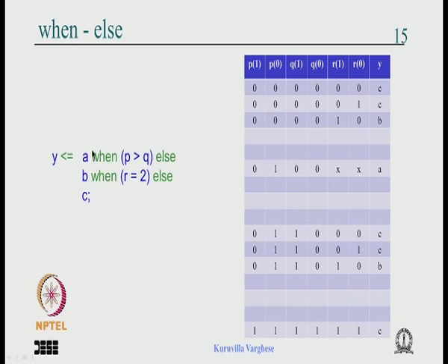You can think of this as a kind of multiplexer: when this condition happens, this input is led to the output; if not, and this condition happens, this input is led to the output. So with various operator implementations, some kind of priority and some kind of muxing happens ultimately as far as the synthesis tool is concerned. We will see how the synthesis tool does this as we go along.